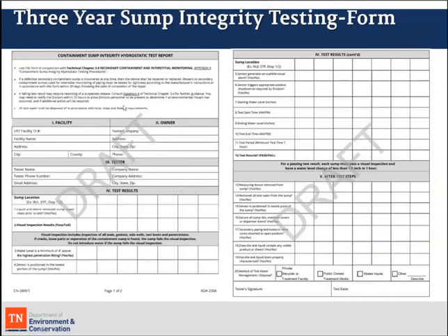It's important that you put all the information that we ask: the facility name and the ID number, owner, all the tester's information, and also do a really good job of explaining sump locations, making sure that you put the product name of, say, the STP sump or the dispenser number with a dispenser sump. So that way, whenever we look at it, we know exactly if there is an issue, where that issue occurred.